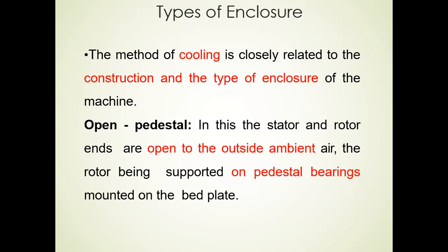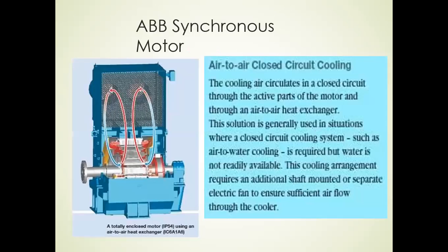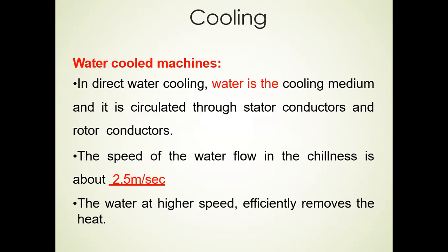That is, for example, we have free circulation of coolant material, inlet pipe or inlet duct circulated, outlet pipe, inlet and outlet pipe, frame surface cooled, integral heat exchanger, surrounding, machine mounted heat exchanger, and separately mounted heat exchanger. Many types are there for different rotating machines.